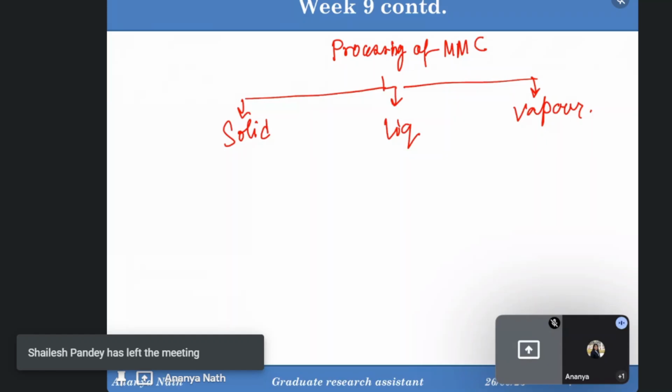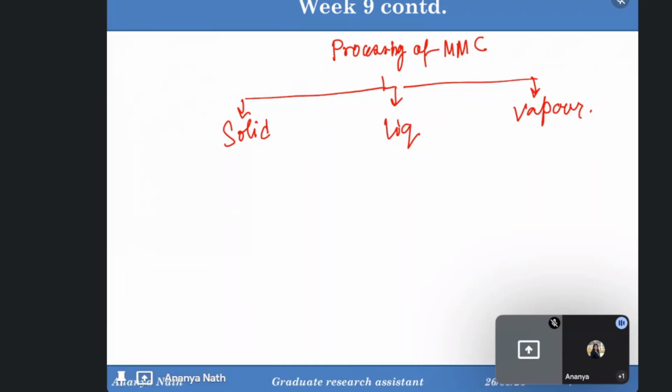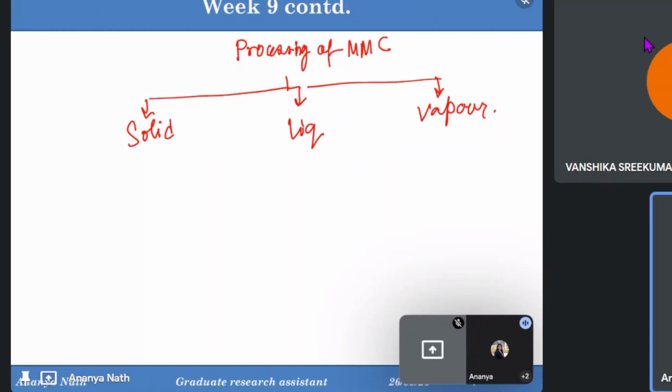Next is the stir casting. Stir casting is a liquid phase process, because it is also used for normal aluminum alloy making. If you can remember, in the case of aluminum silicon alloys, there was a topic on primary silicon growth, the twin boundary effect, and the undesirable growth of the silicon in the direction of the twin plane. There, strontium, barium, and sodium are generally mixed at 0.02% in the aluminum alloy to control that unneeded Si growth, and to alter the Si growth region or the plane.